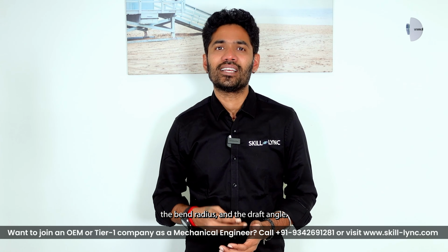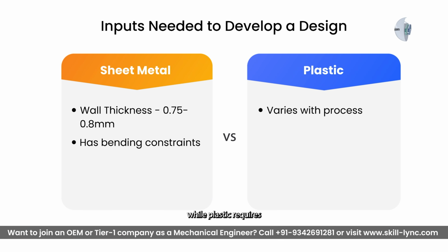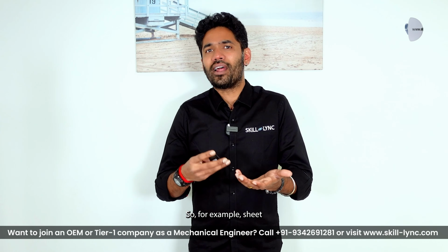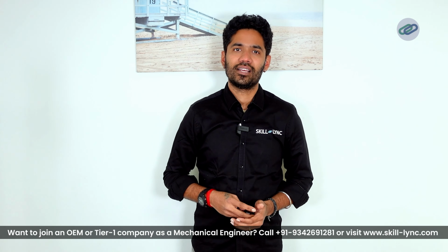The bend radius and the draft angle. Sheet metal has bending constraints while plastic requires draft angles only for mold release. So, for example, sheet metal can have plus 7 degrees draft angle, whereas in plastics we are talking about only plus 0.5 to 1 degrees.